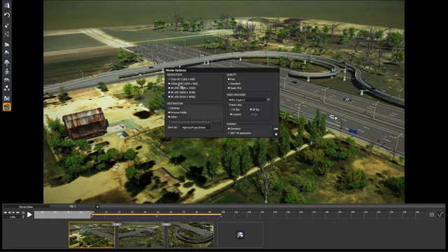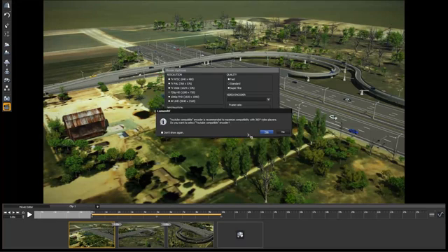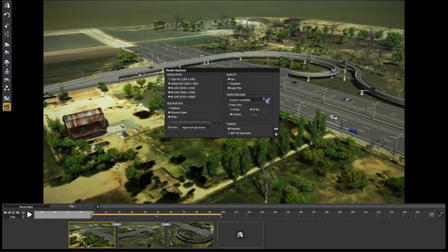And then you'll notice there's a new setting here that says I can output either standard video, which is flat video, or 360-degree VR video. And then we have some choices on the video encoder, and you can indicate that I want it YouTube compatible. When you indicate YouTube compatible, it will output an MPEG file and will inject the necessary metadata so that when you upload it to the YouTube website online, it will automatically have all of the data attached to it to tell YouTube that indeed this is a 360-degree panoramic video.